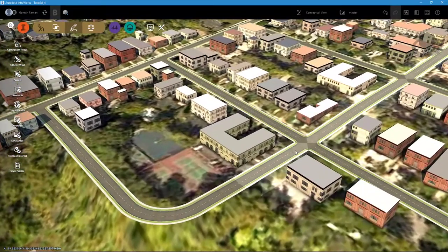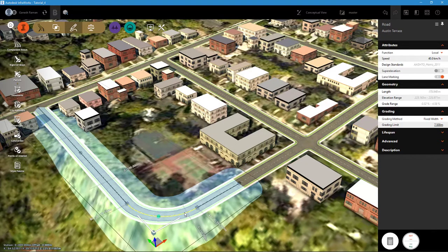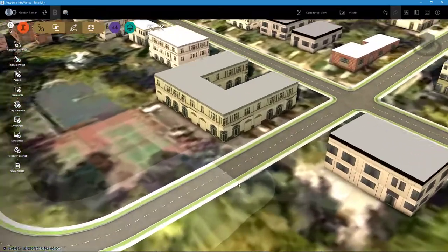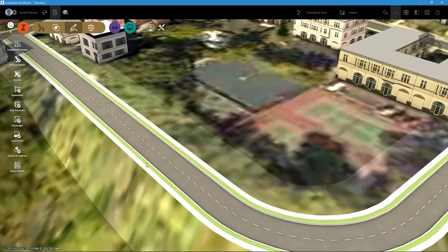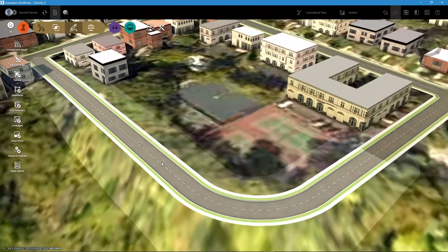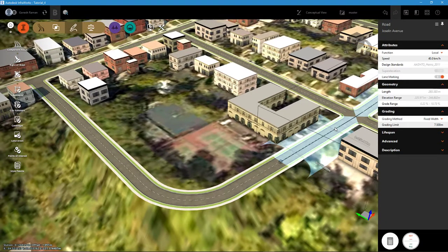and Jocelyn. And the component road, because I started at Austin, stays as Austin until it joins Jocelyn over here. A clean connection with matching sidewalks and green space on either side of the road is maintained because I converted this road into a component road.